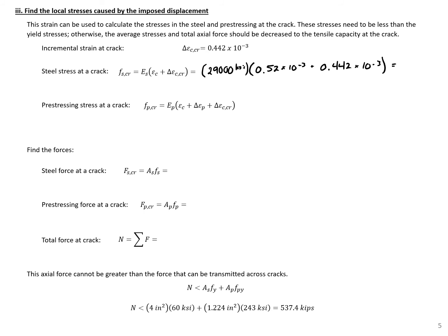And solving this, we'll get a stress of 27.9 KSI. We can see this value is less than the yield stress of our steel, so we're okay here.